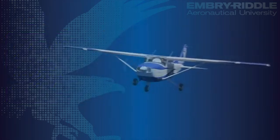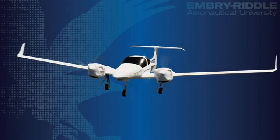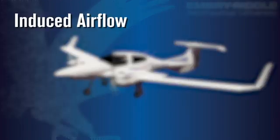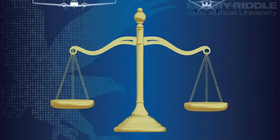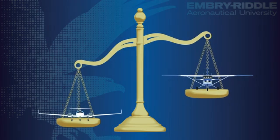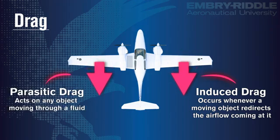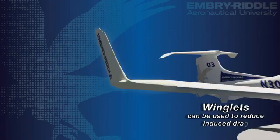Lift. The power plant is mounted to the front of a single-engine aircraft. On most light twin engines, the power plant is mounted on the wings. This results in induced airflow over the wings. Induced airflow is air from the prop wash and causes increased lift production. The added lift is beneficial since most light twin engines tend to be heavier than single-engine aircraft. Drag. Both induced and parasitic drag are present. Since multi-engine airplanes tend to create more lift on the wings, they may have winglets to help reduce induced drag.